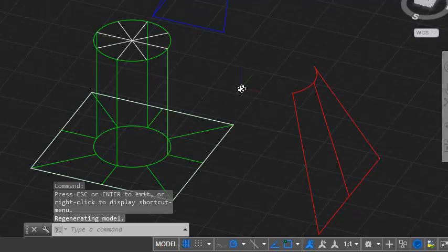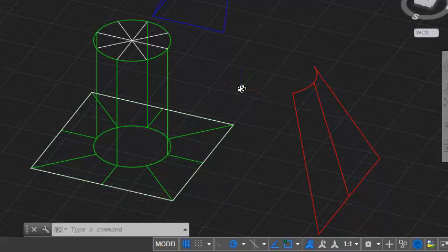When I was showing you some of those drawings, the pictures of the actual parts, I was describing, oh, here's a weld seam here. This part's been made in halves, which was how those were made. I want to show you my preferred way to make it, which usually stems from running a press brake a little bit and being able to handle the part on the press brake a little easier. That's my experience working with large, not just small ducting squared arounds, but large pan squared arounds and heavy duty 10 gauge, 3/16 inch thick material. It gets really hard to handle if I'm making it out of some of these configurations.